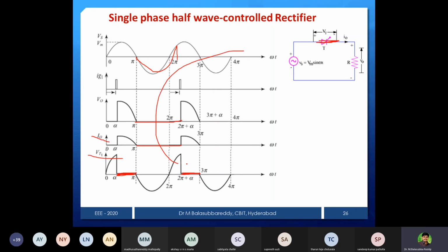And this is the sequence you can represent for a thyristor. The previous one is a diode. This one is a thyristor. You can easily see the difference between the diode as well as the thyristor. Because you can control here, instead of starting here, you want to start here, you will get this as the output. That's all. And if you reduce further, this is the output. Like that, you are able to control by passing the gate signal at the instant you want.